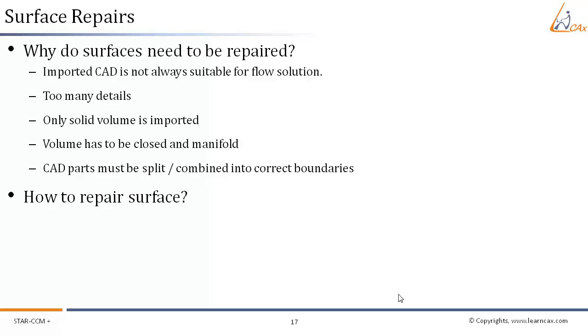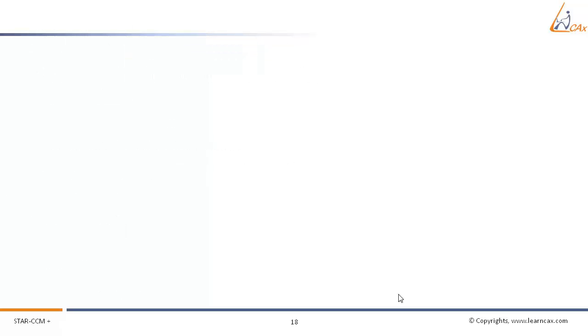How do we repair imported CAD surfaces in STAR CCM+? For simpler geometries, we can use the manual repair tools. But for complex CAD models, we need to use tools like Surface Wrapper. We will see this in detail in the geometry section of our course.